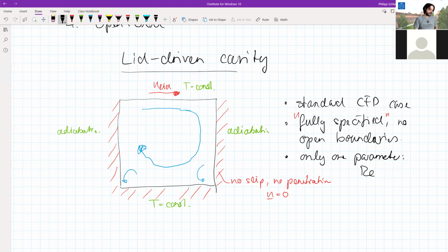Okay. So now we talked about the actual case, and now we would like to translate that case into something that we can apply in our CFD code. If you think back to the very first lecture that we had together, when specifying the physical case, at some point we need to specify our mathematical model of this case, so that we also specify the equations, the boundary conditions, and the coordinates and the geometry and all of that.